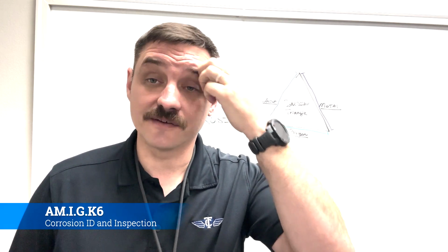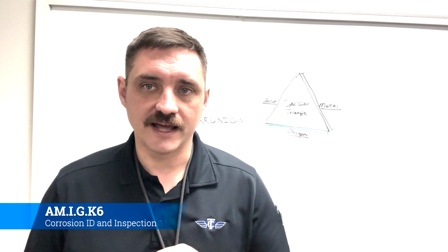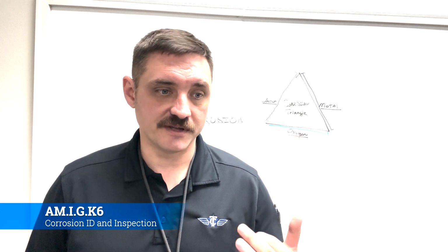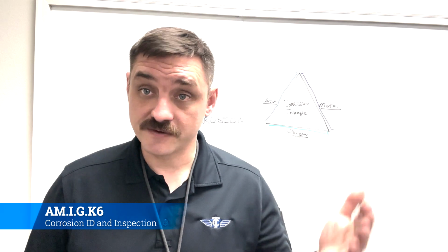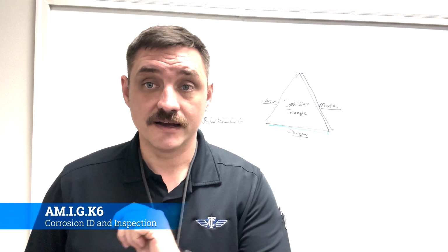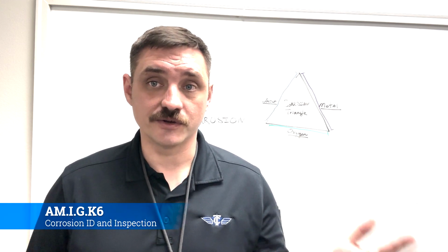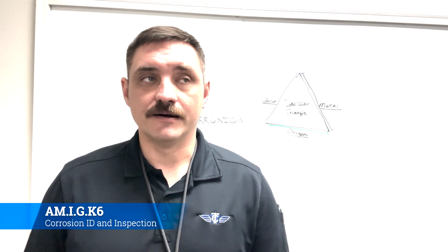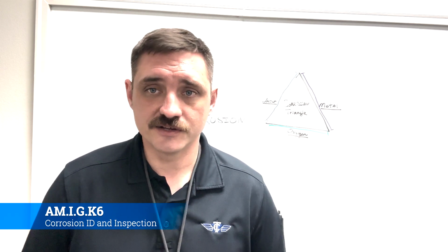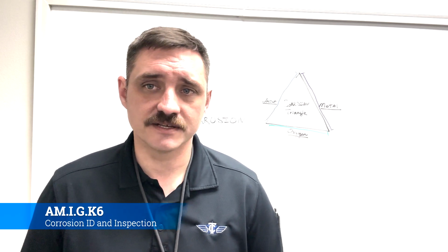But most of that stuff is baked into the maintenance process, so you won't necessarily have to call out for NDI or have to go do it yourself. Most of the time, you're just going to be doing a general visual inspection, a GVI, and I'm going to start saying GVI more often. You'll be doing GVIs, and then only on condition do you call for NDI. But most of the time, you'll find it without, and you won't need NDI. It's only in rare circumstances that you actually have to go that far.